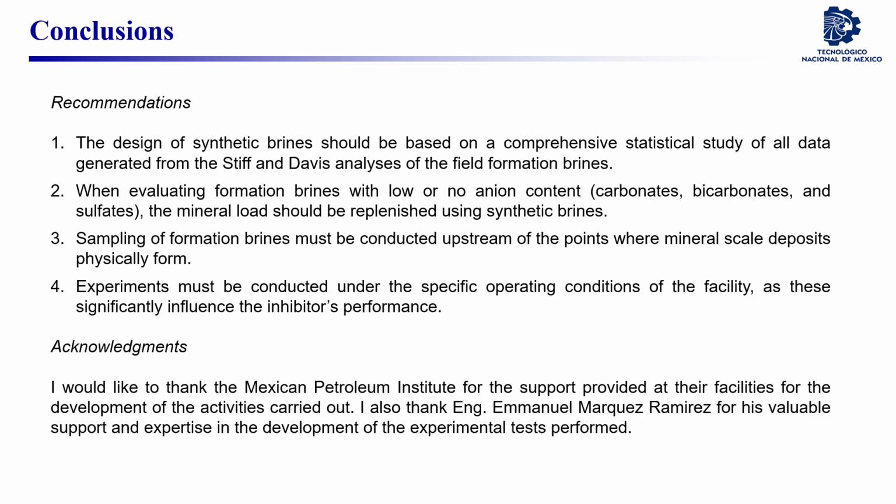Recommendations: the design of synthetic brine should be based on a comprehensive statistical study of the data generated from Stiff and Davis analysis of formation brines from the field. When evaluating formation brine with low or no iron contents, the mineral load should be replenished using synthetic brine. Sampling of formation brine should be conducted upstream of the location where mineral scale physically forms. Experiments must be carried out under the specific operating conditions of the facility.